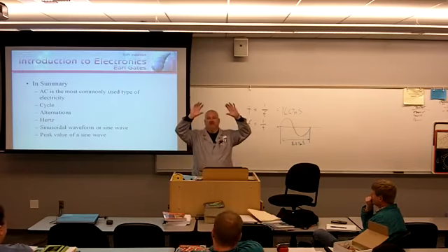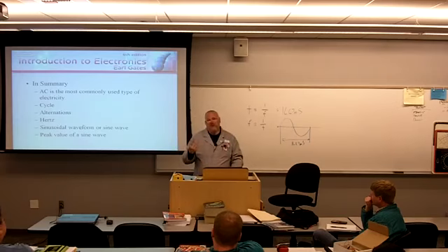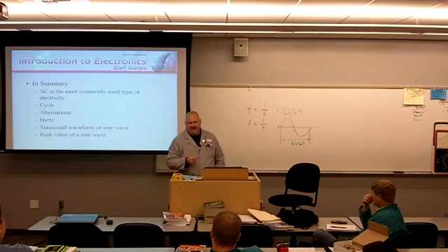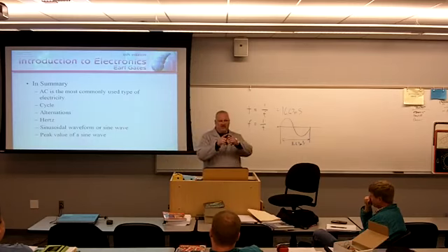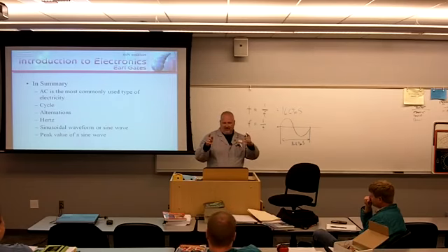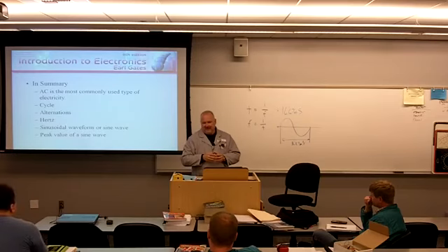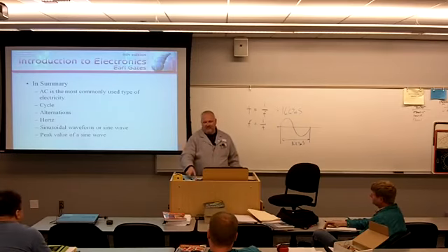But one of the things that I had was an oscilloscope set up with a function generator. If I questioned the computer, I would take that signal and route it to the oscilloscope, just like we have here in the lab. I'd get a function generator, just like what we have in the lab, and feed the input into the function generator, out of the function generator into the oscilloscope, into what's known as my x-axis. So my y-axis is the unknown frequency. The x-axis is my known frequency. And I could mix those 2 signals together on the face of my oscilloscope.